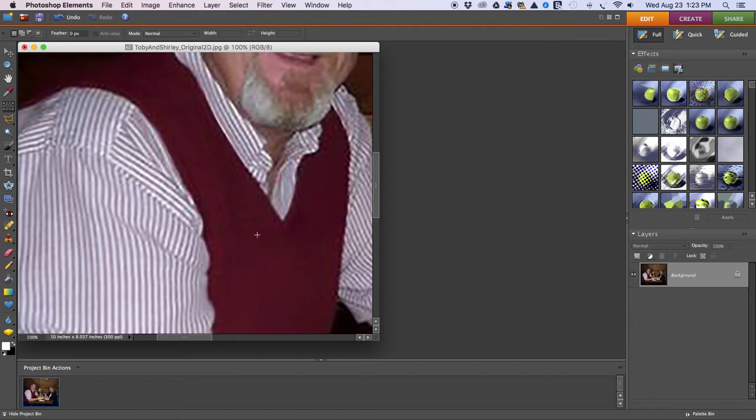And when you do your shifts, for every tap of the arrow key that you move an object, you're wanting to move it by one image pixel, but it's actually going to be moving it by one screen pixel. And to make sure that you're consistent, you want to make sure that one screen pixel equals one image pixel. So you have to view it at 100%.